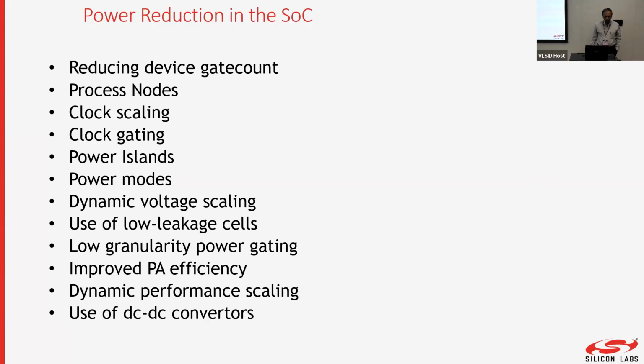And whenever you want to change the voltage, if you do it using a linear regulator, it's no use, because the linear regulator burns the extra energy that you are trying to save by going to lower current and lower voltage. So use a DC-DC converter: a transistor-based chopper and tank circuit, which converts voltage just like a switch mode power supply. You do it more efficiently. So all these techniques are there. We have to use all of these, but they're not enough.